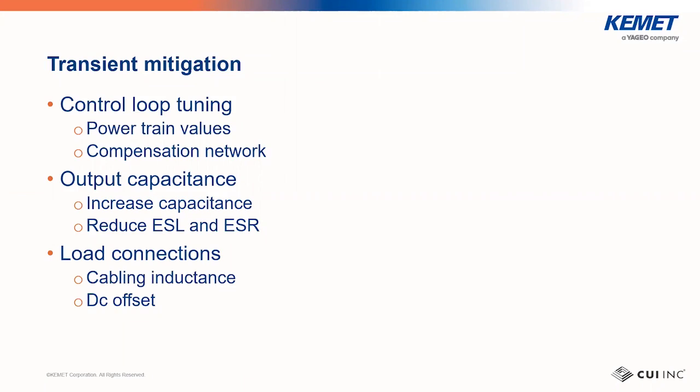It should be noted that there's a limit to the amount of capacitance that may be applied to the output of many power supplies. Typically, if too much capacitance is applied, it can send the power supply into overcurrent protection on startup, as the capacitors represent a short initially. They're also part of the control loop and can affect stability, so care should be taken when adding bulk output capacitance.